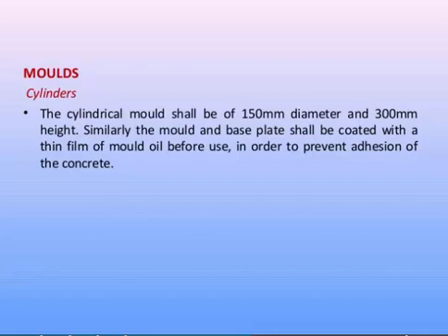If we are discussing the curing of the specimen, the cast specimen should be stored in a place at a temperature of 27 degrees plus or minus 2 degrees Celsius, as per the Indian Standards, for the time of addition of water to the dry ingredients. After that, the specimen should be marked, removed from the mold, and immediately submerged in clean fresh water or saturated lime solution and kept there until taken out just prior to the test.